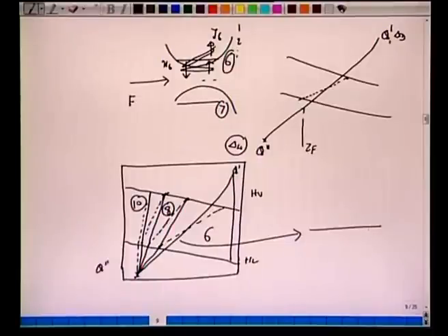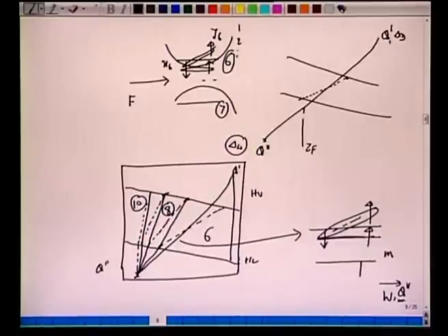The liquid which leaves the plate is in equilibrium with the vapor phase. So this would be the tie line. And the liquid and the vapor which arrive with this liquid here, this would be the solid line. So now the difference point is given with this Q dash with respect to the bottom product, which is your W, and it carries the enthalpy of this Q dash. So if you choose any nth plate M, the liquid and vapor arriving here and the liquid leaving here, the difference between the two, enthalpy with the molar flow rate, is conserved with the W and Q dash, which we have marked as the del W point.